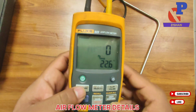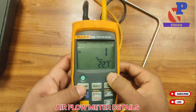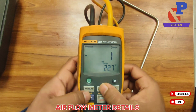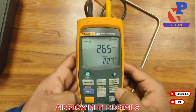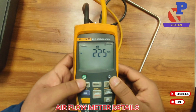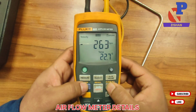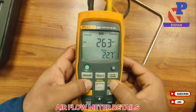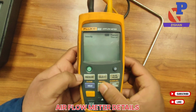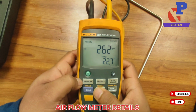Suppose we are going to take the velocity inside the duct. First we have to make it zero sample, and for that we have to reset all the previous data. First we press the yellow button, and after that we press all clear, so that all the samples are cleared. After pressing the enter button we calculate the zero.